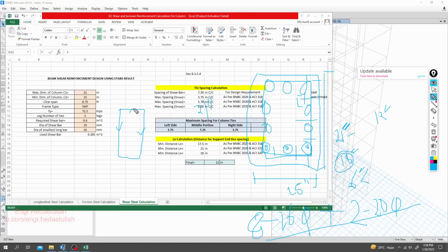And also if we provide here an extra cross tie or tie, then it's known as 3 leg. And also if you provide some stirrup like that or tie like that, then it's known as 1, 2, 3, 4 leg. So you have to provide it here. I'm considering we'll provide like that, so I'm considering it will be 4 leg.